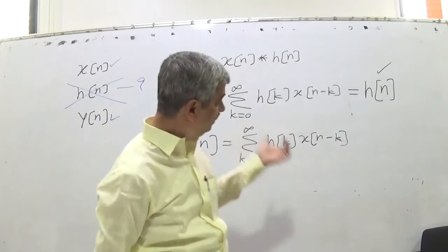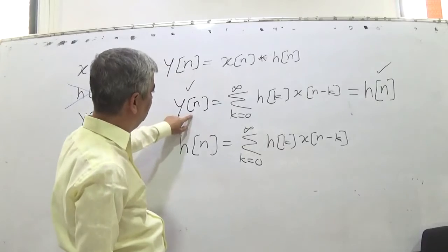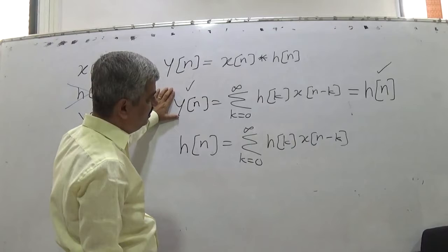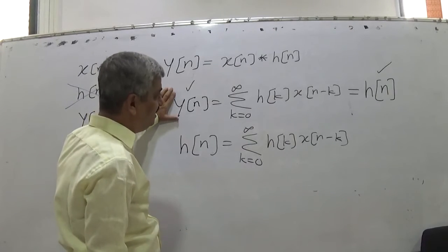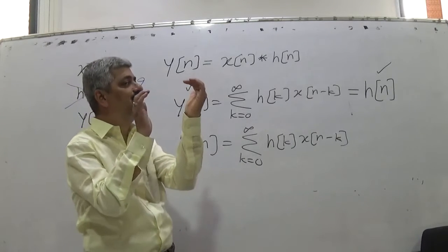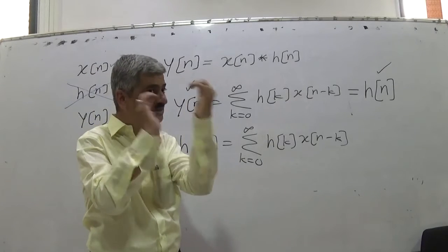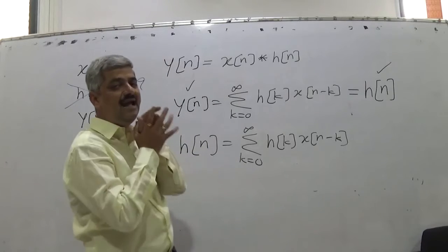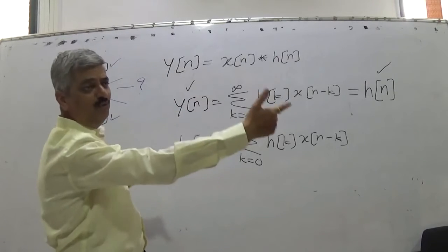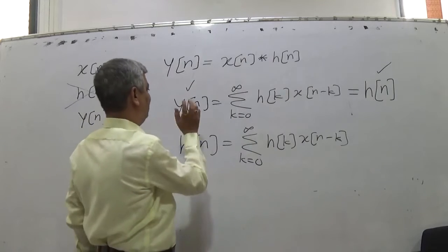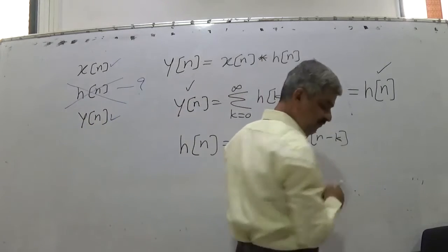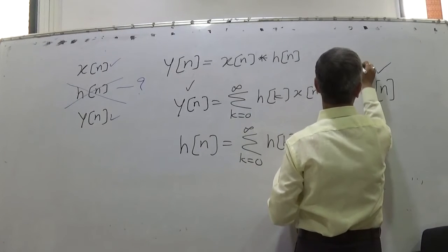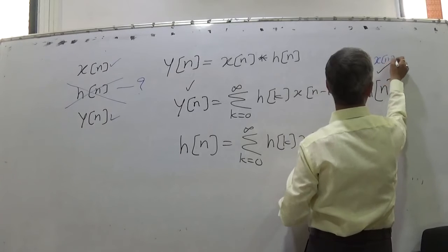Now, if I have this equation, convolution sum, can I have some special test input which if I give, the output would be system sequence? So I have a system with me. System I don't know, but system I possess. I have the system, I can use the system, I don't know the system. Can I apply some test input such that what output I get is the Hn itself? So for what xn would this be Hn?